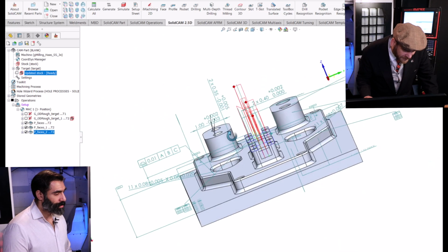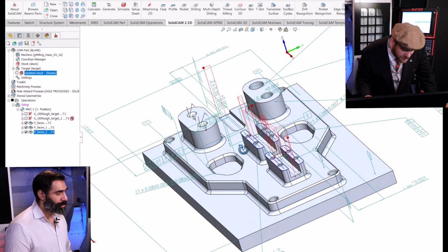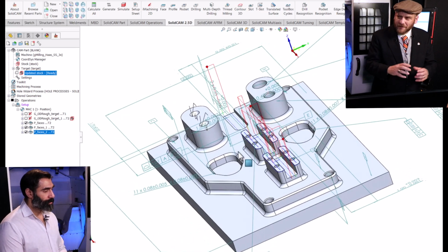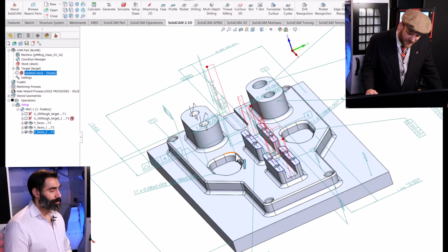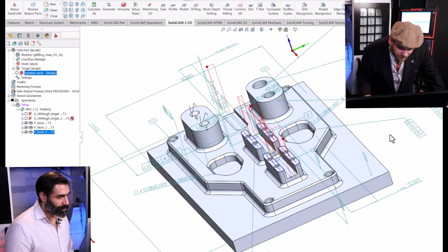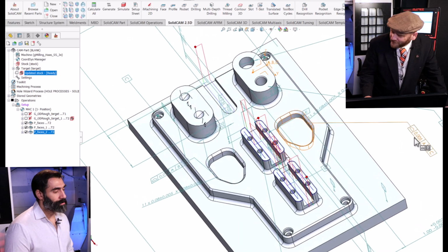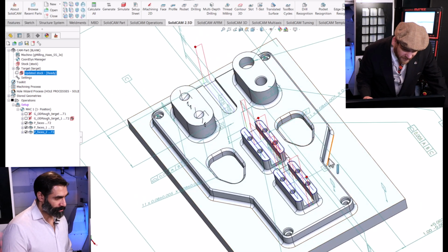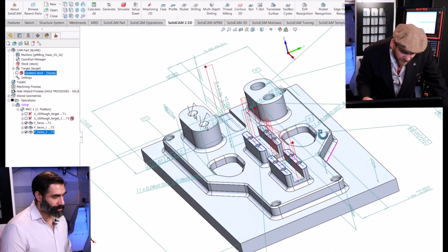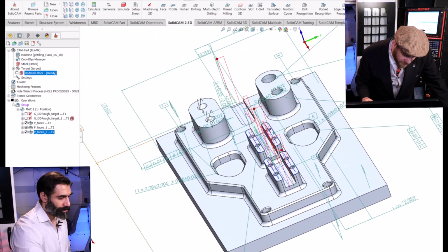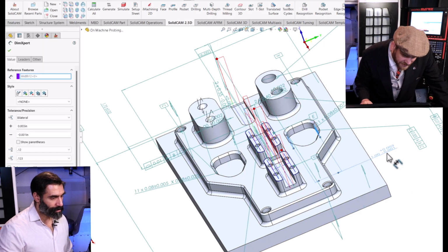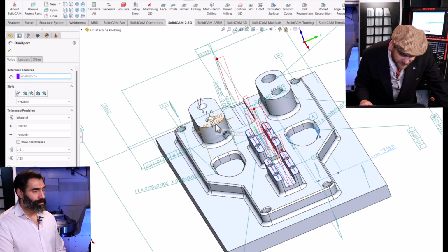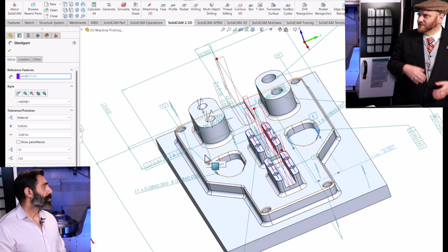And the width of the pocket is +2, -3. So I can be a little more open with it. I have an extra chance to be able to remachine that if I need to. The other pocket here is a profile tolerance of 5 thousandths, which is much tighter. And also, in the top, right here, we can see that that has a different tolerance on it. That's +3, -1, where this one's +2, -3. So I'm going to handle these differently.